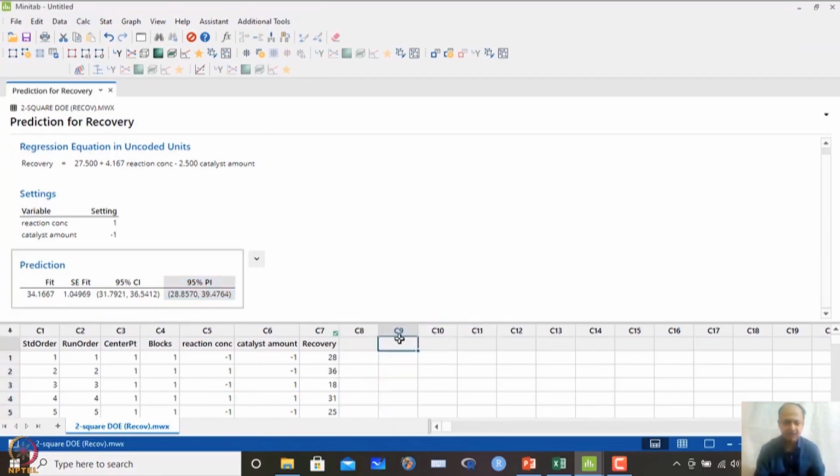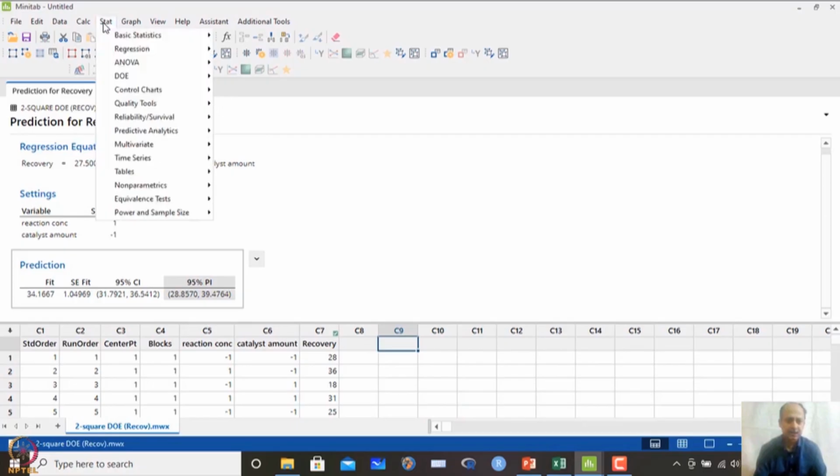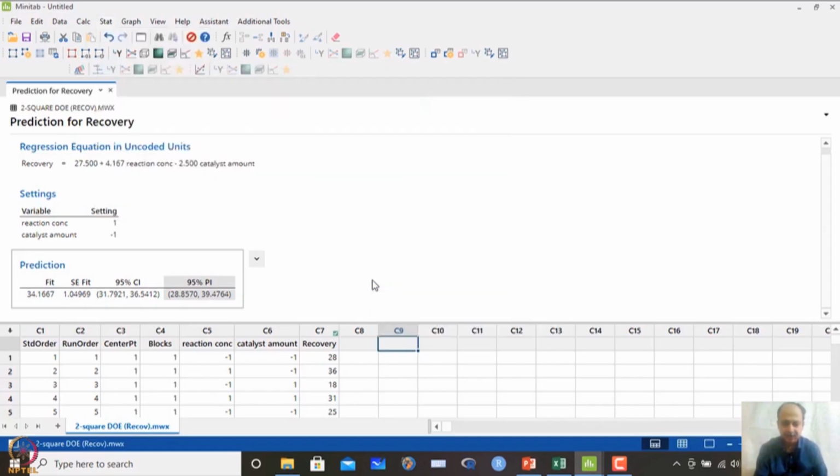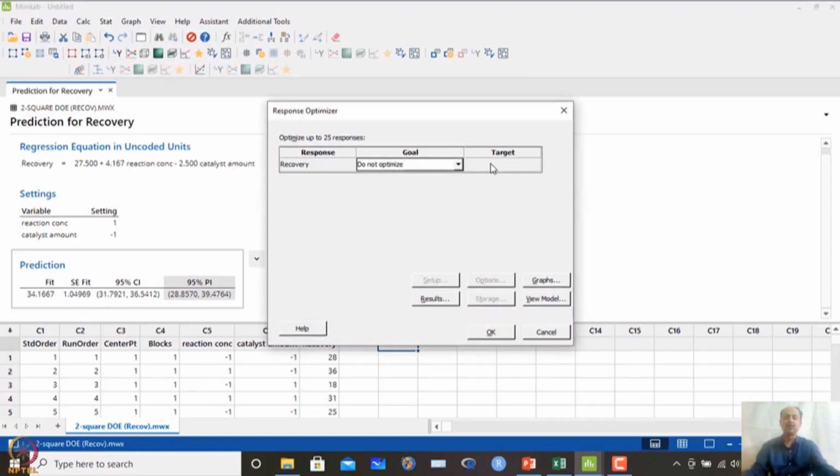We do not need the residuals over here. We have seen the surface plot also, and what else we can do is make a response optimization. We can also see the optimal value if I go by the formal way of optimization, using the desirability function approach that MINITAB uses. Desirability we will discuss afterwards. In this case you can also get the optimal combination, because if I assume both are continuous, MINITAB will work automatically and figure out the optimal combination using a desirability function.